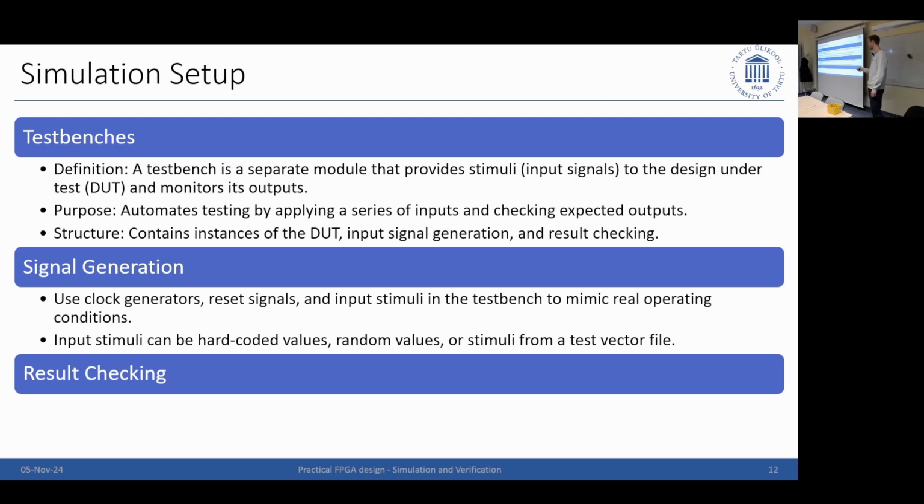Ideally, of course, you would consider the test vector and how this all looks in your design draft phase. So in a preliminary design, when you draw out the architecture, when you're experienced enough, you know what design blocks you want to have, you know what simulation blocks you have, what you need to simulate, and how you need to simulate it. Then you draft it all out, you make work packages and tasks out of it, and then on to-dos, and you do not go first to the simple, annoying thing. You try to write it a bit bigger overall. So it's more efficient in the long run. Otherwise, you have to rewrite your test bench 1,000 times, and it's annoying.